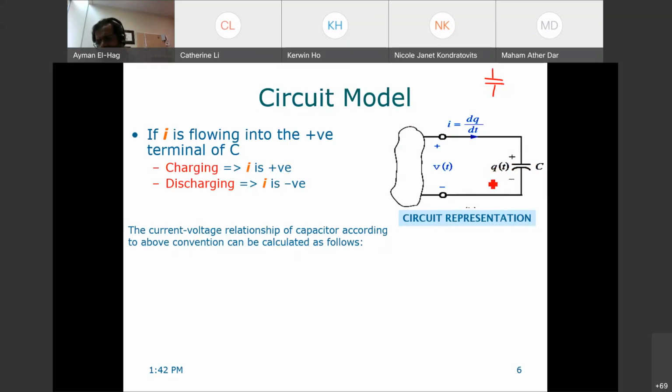Why is that? Why does this line have this slope? This is to tell you that this terminal has to be connected to the positive, and this has to be connected to the negative. What if I reverse? If you reverse, the capacitor will explode. If you go to YouTube and search for explosion of capacitors, wrong connection, there are many cool videos, but don't try this at home, of course. When you reverse the connection of the capacitor, they explode. So this is intended. So you have to know where is the positive and where is the negative when you connect them in a DC circuit.